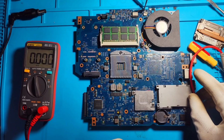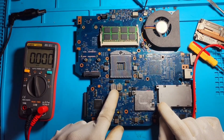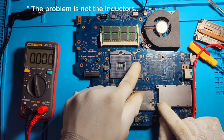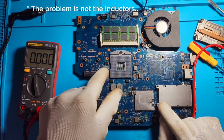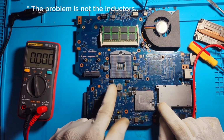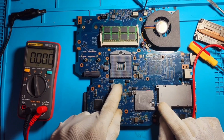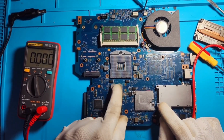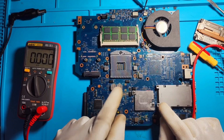I'm thinking to replace this coil here first and go with the capacitor after, so that will be a good measure, because we have many capacitors here and we can't decide which to replace. So we will first replace these coils and check if the voltage rise improves with the oscilloscope.